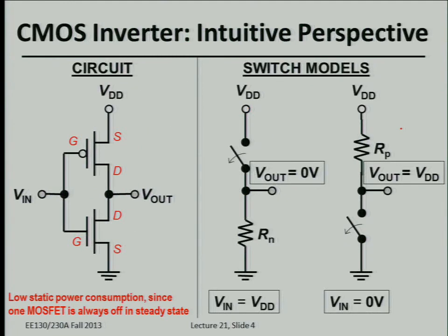Okay, so now let's look at a digital logic circuit. So looking at a MOSFET used for digital logic. Again, this is what we went over last week: a CMOS inverter comprises just two transistors, one NMOS and one PMOS. And the key is that the gates are tied together, electrically connected. So whatever voltage, whatever signal you want to apply to the inverter, it goes directly to the gate of each transistor. And then the drains are tied together, and that way they can drive the output voltage to be either high or low, depending on the input.